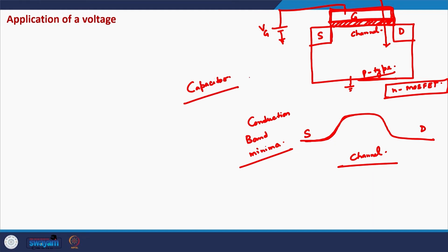So, the MOSFET, from gate to body, gate to the substrate, in this direction the MOSFET behaves like a capacitor, and in this direction from source to the drain side, when we have a channel, when we have an inversion, then this will act like a conductor. Okay.